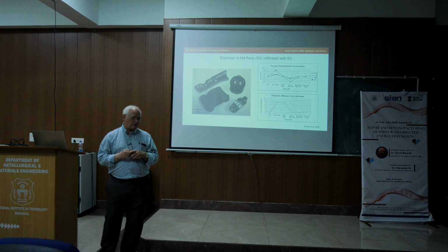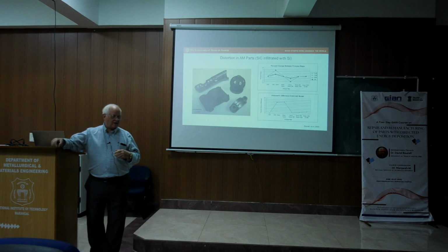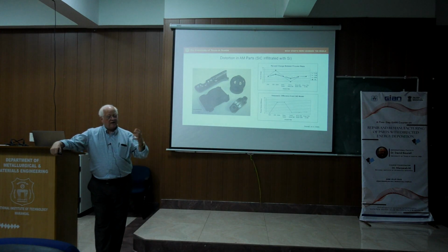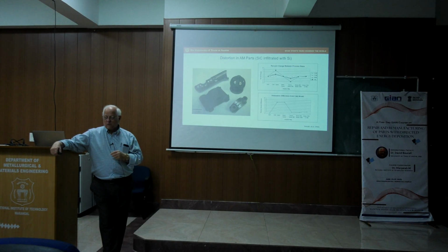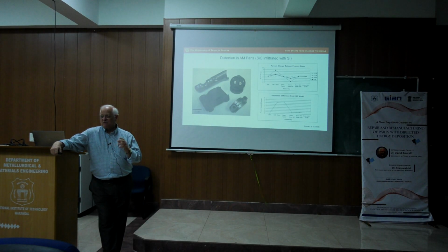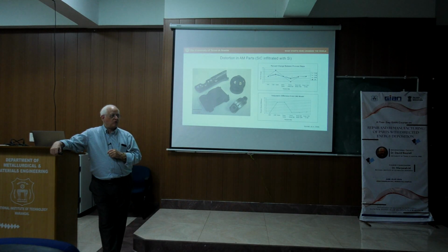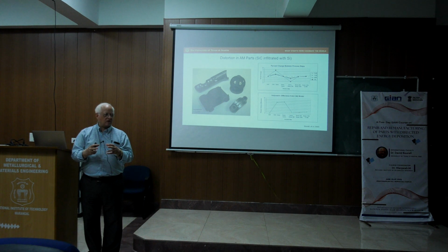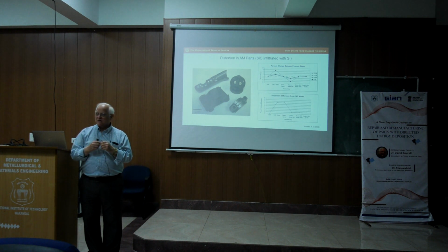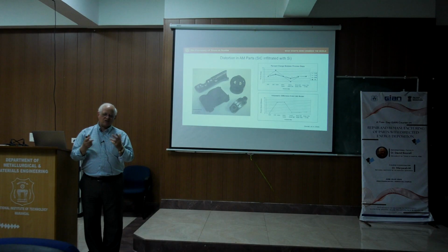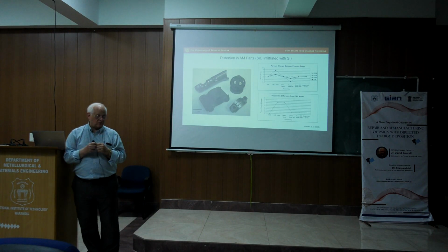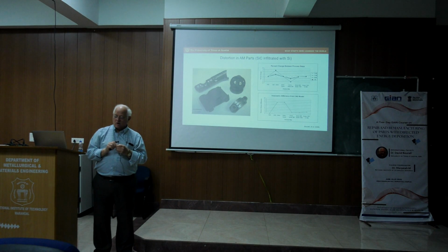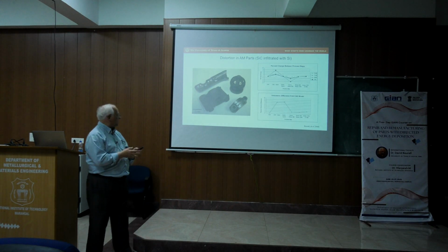And then what we would do, and this is standard practice for producing reaction bonded silicon carbide, is we would take that preform, it's a porous preform, we would heat it up to about 1750 centigrade, very high temperature, and then we would wick in molten silicon metal. So what we have at the end of the day is a framework of silicon carbide that also has silicon metal in it. And again, it's a standard commercial grade material, reaction bonded silicon carbide, in whole shape. So that's what all these parts are.